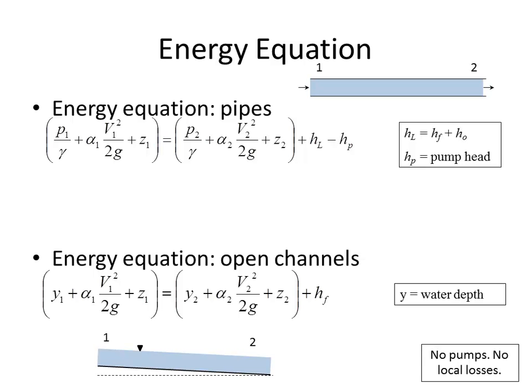Is alpha considered to be negligible again? Yes, yeah. Especially true in open channel flow because in open channel flow, the velocities are much lower than they generally would be in pipe flow. And there are exceptions to that. Flow over the top of a dam spillway does get moving pretty fast. But most of the time, especially in natural channels, the slope would be maybe at most 2%, 3% slope. And so the velocities will be pretty mild by comparison.